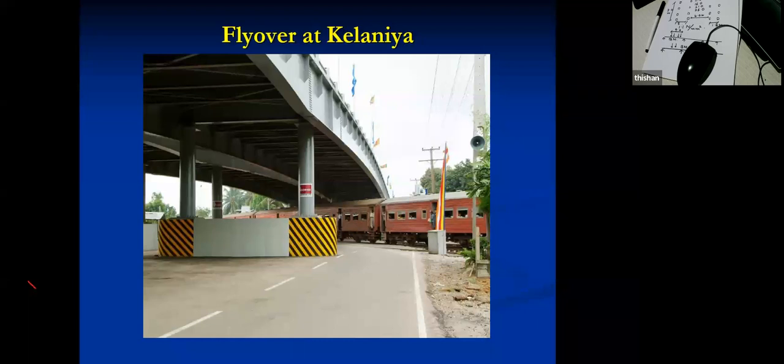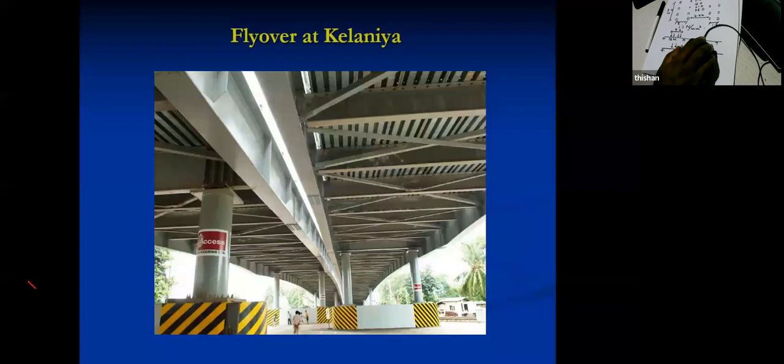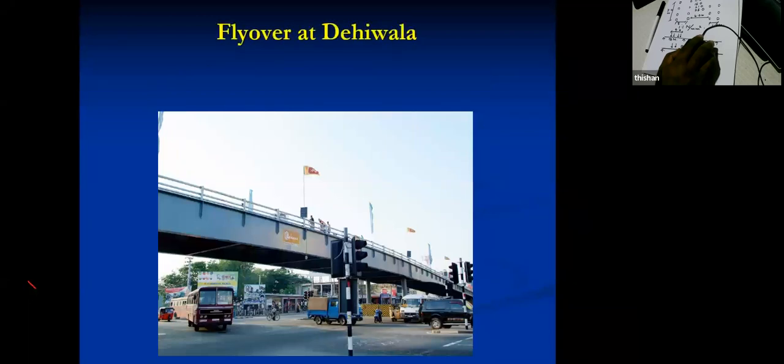So there are people and technology in Sri Lanka to manufacture bridges in Sri Lanka. So why I told you that is, otherwise we think whenever we have a big steel bridge, we have to import it, as we have done in this particular case from England. And then this is one figure, and this is how it looks from below, with so many bracing arrangements, and even a lot of web stiffeners for the beam to prevent buckling of the steel sections.